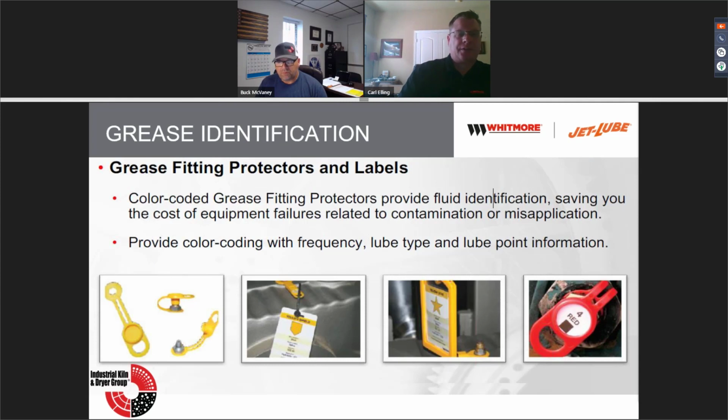Going back to the grease fittings and your color coding type labels. So these are the caps that you can put over the grease zerks. This will help reduce the amount that you have to clean, but you still need to wipe them off and everything. But it'll be color coded, and that could be by the type of grease. And you can put a number up here, which is a little white label, and it can be a different number. It could be a letter. It could be something like that. And that could be represented by here.